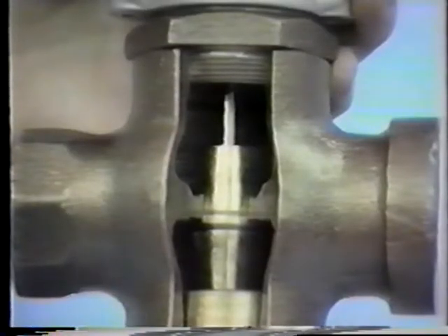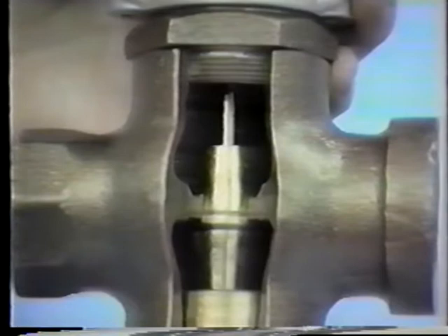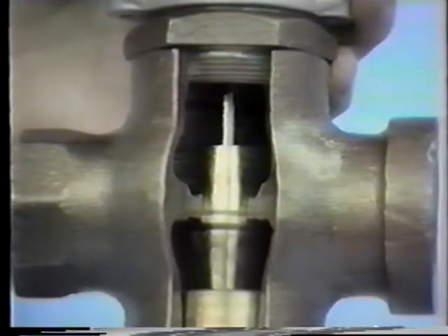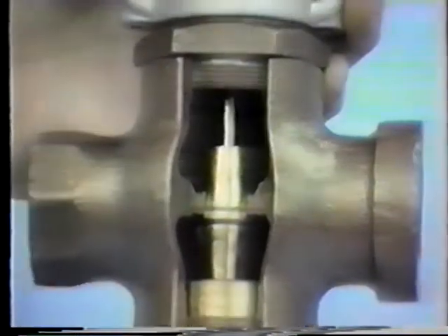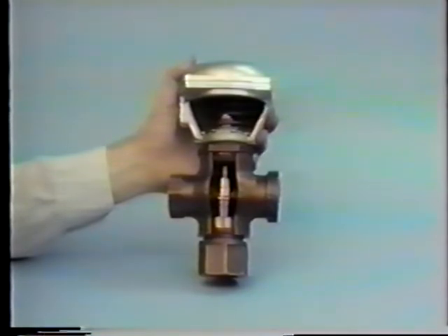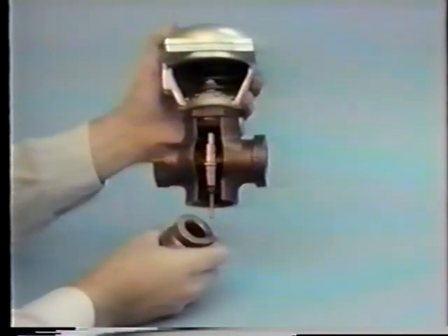This cutaway of a three-way valve shows a different style of valve plug. As indicated by the previous line drawing, the plug itself is tapered towards both ends and has a metal surface, closing against a metal surface. The valve is shown in the normally closed position with full flow through the bottom of the valve and out the left side. The bottom seat is machined into the threaded assembly, which is screwed into the bottom of the valve. The stem and plug assembly are removed through the bottom of the valve after the bottom plug has been removed.